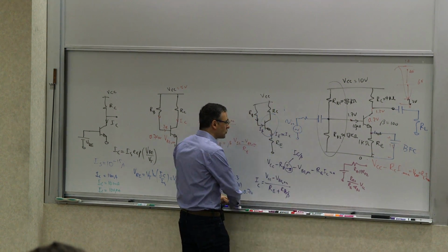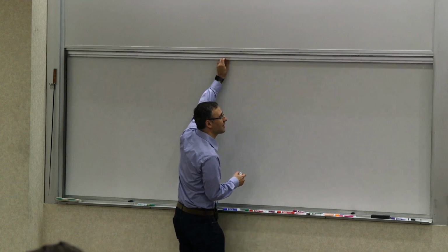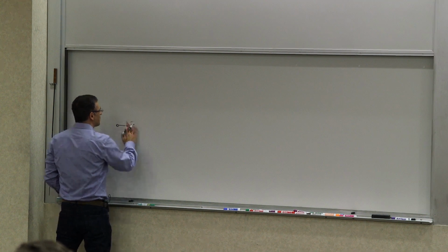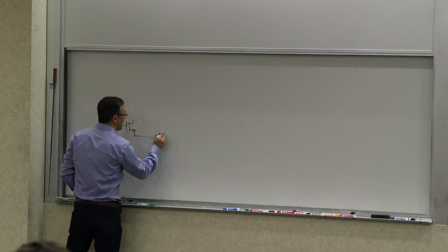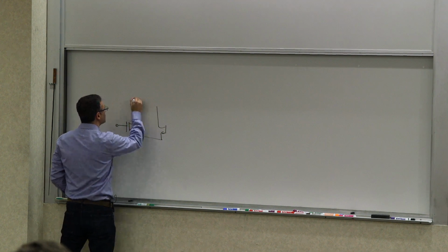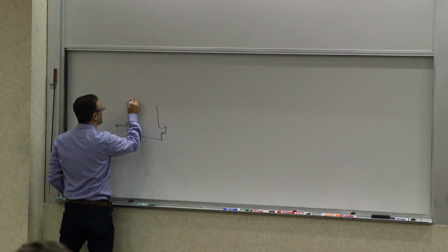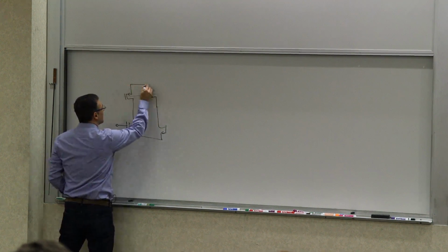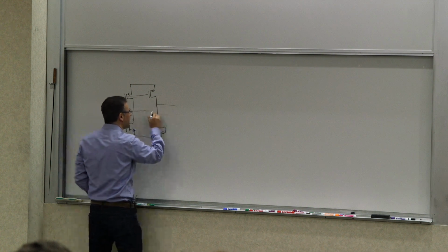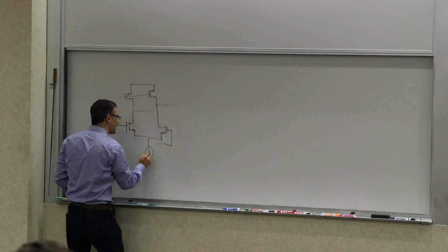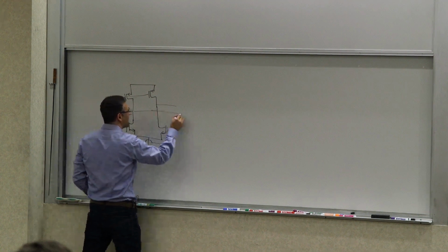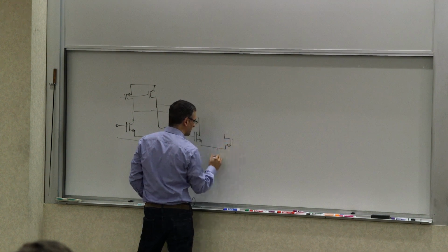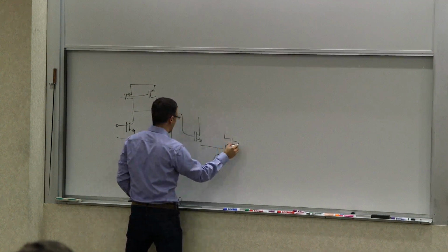So instead, you go to stages like the differential amplifier that allow you to cascade without having to be DC coupled. So you can have, for example, an amplifier stage, let's make it a fully differential one. And then you can take it to the next level. This is biased with a current source that would go to the next stage of amplification.